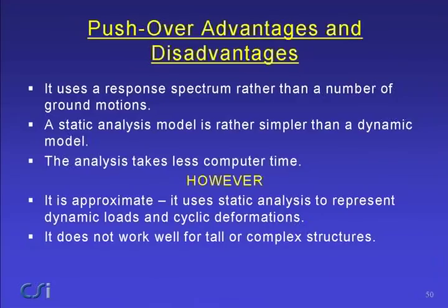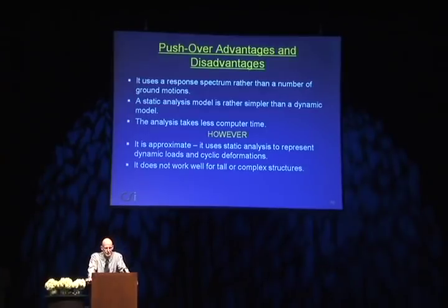Advantages and disadvantages of pushover: you use a response spectrum rather than ground motions. The static analysis model is a little simpler than dynamic, not a lot, but somewhat simpler. And the analysis takes less computer time. However, there are major caveats.